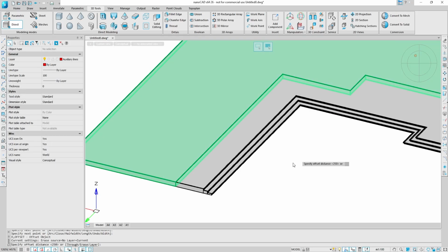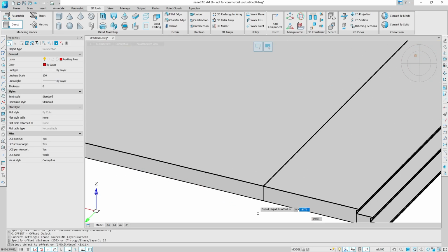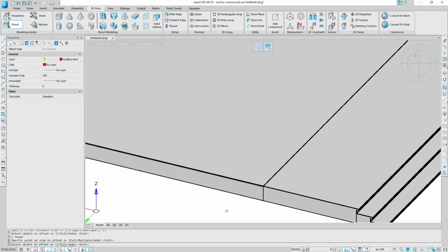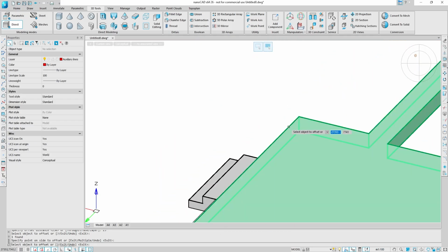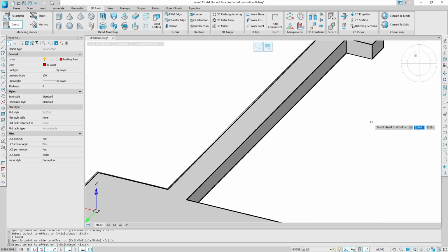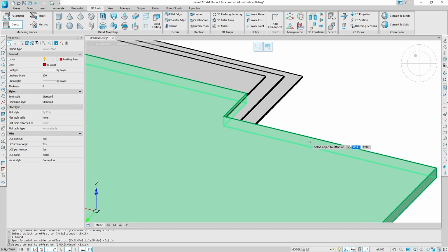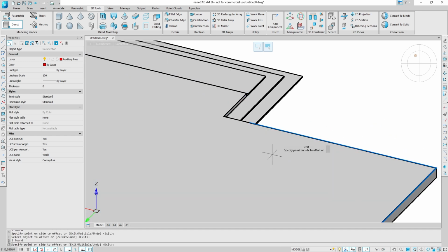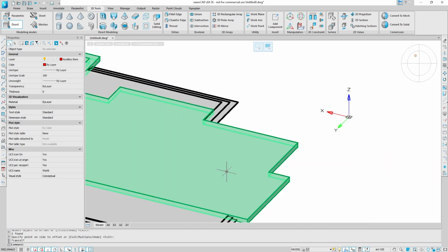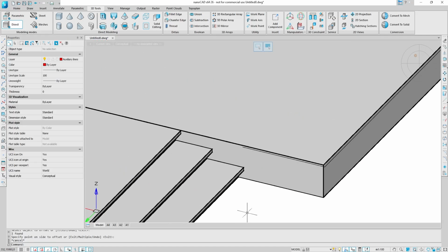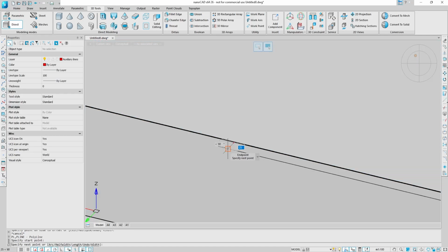For each polyline you create, add a second contour at a distance of 25 mm. First select the desired polyline, then activate the offset command. Set the distance and offset angle. To make the contours closed, draw the missing segments.